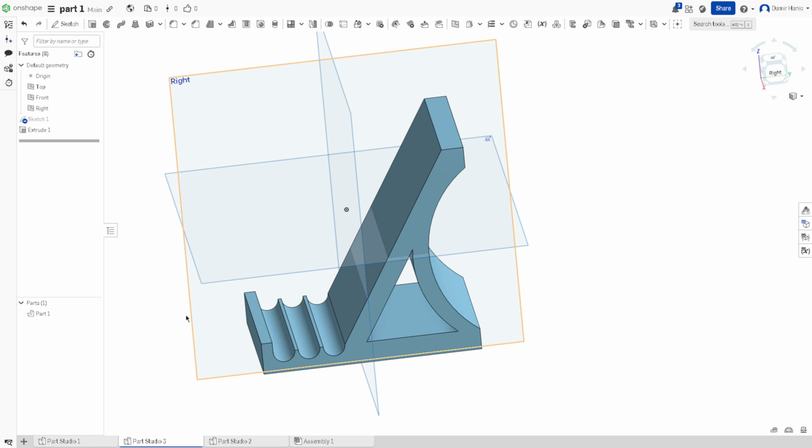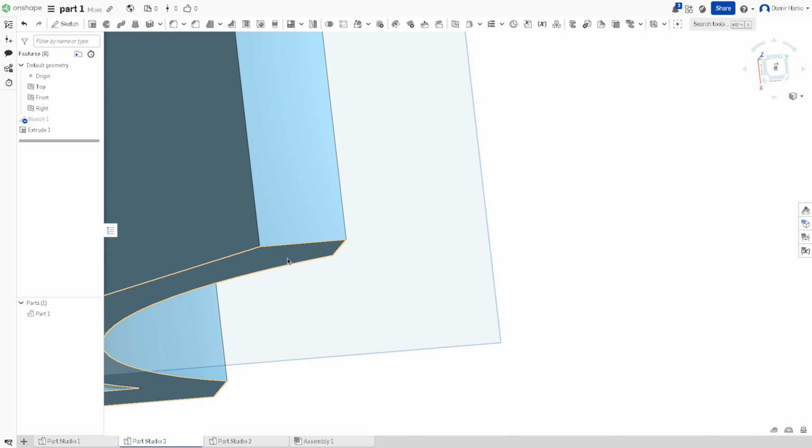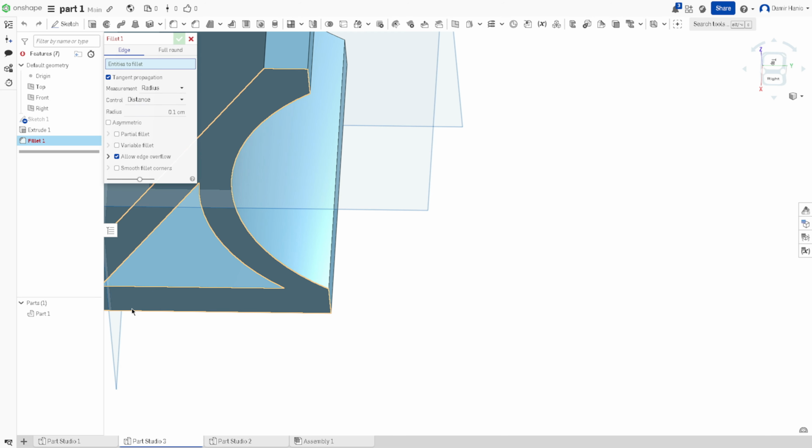We have tools called fillet and chamfer, which make corners look rounded, or remove the 90 degrees, so it makes it look nicer. This is important when 3D printing, especially filleting on the sides, because when the machine starts to add material and goes directly 90 degrees from the side, something's going to not work, and we want to minimize our problems. So we're going to say 0.5. Perfect.